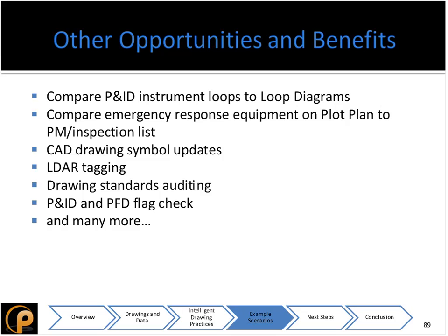And then imagine if you're going into a PHA, imagine doing a flag check on all of your P&IDs in that unit or that facility so that you're not spending time in your PHA trying to figure out where this pipe connects on what drawing. If you have flags or blocks, you can do that extraction and then do all that comparison beforehand in some spreadsheet, maybe with some routine, or maybe with some built-in functionality in that CAD software. And you can imagine doing the same thing for PFDs.